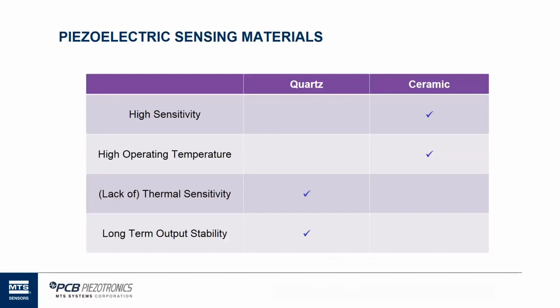The ceramic crystal design is higher sensitivity inherently. We can build those so that in a given crystal cut, whether it be shear or compression, we have the ability to grow those crystals so that they have a much higher piezoelectric output for a given strain. They have the ability to go much higher in temperature also. That's the advantage of ceramic.